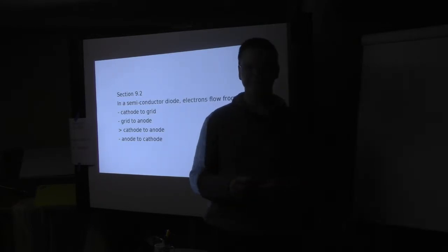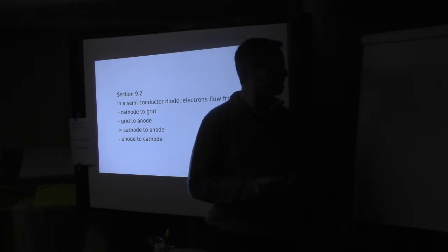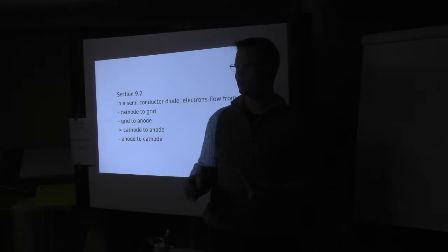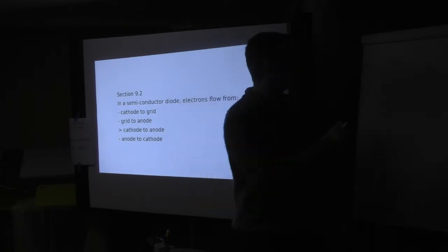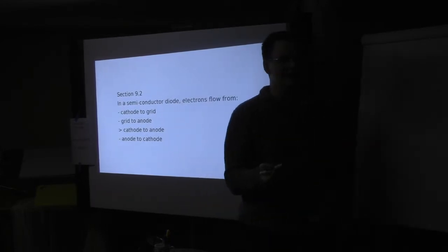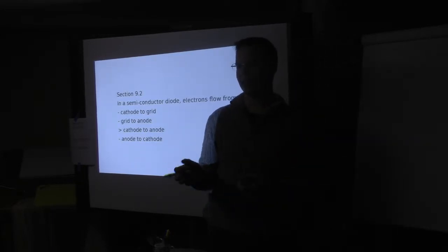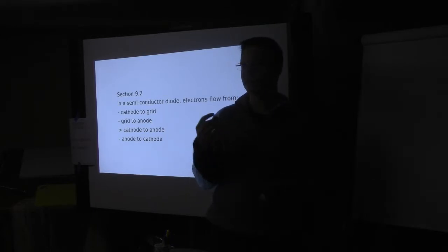That's a silly question, but is that why the diode's drawn that way? So it's almost like an arrow pointing which direction it's going to flow? Exactly. Everything works on current flow. You just kind of know that electron flow happens. So current flow moves this way, but the actual diode properties of electrons let it flow the opposite direction. So our little negative electrons here, they actually flow the other direction through the diode. But the diagram has it reversed because it always talks about current flow.